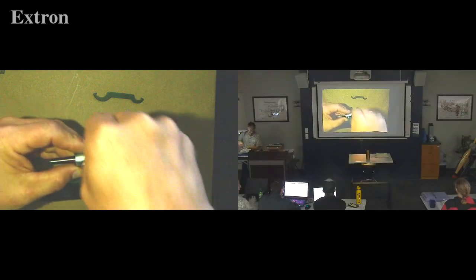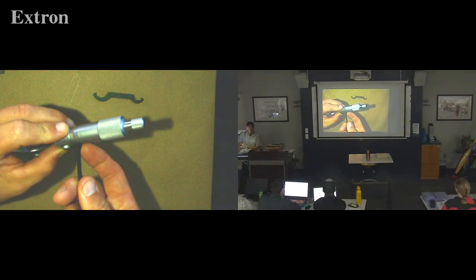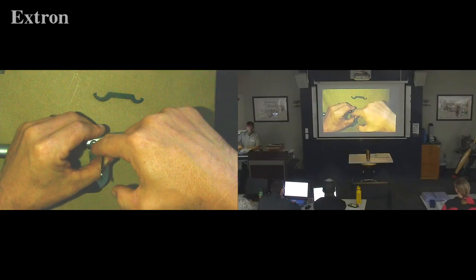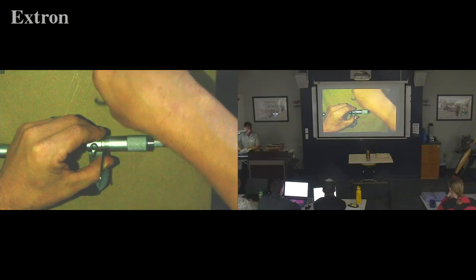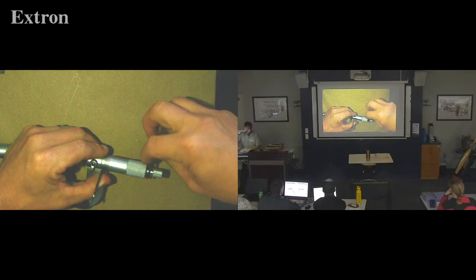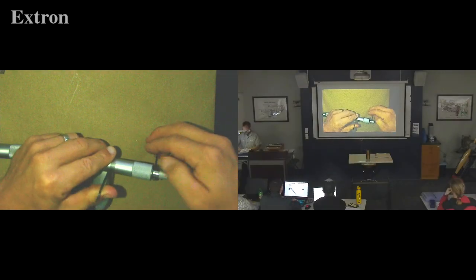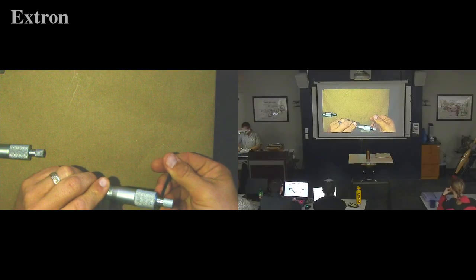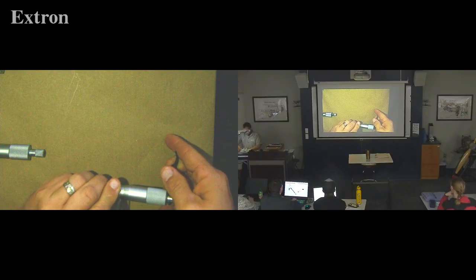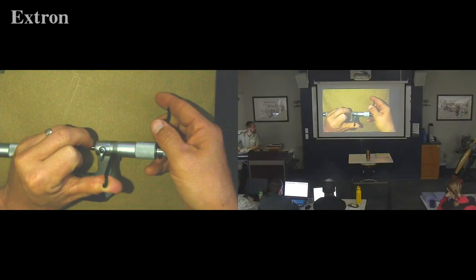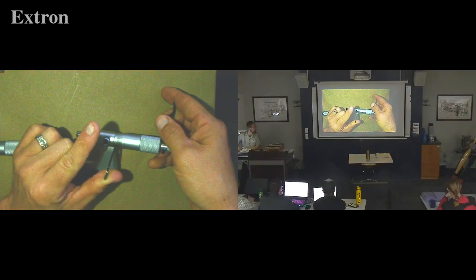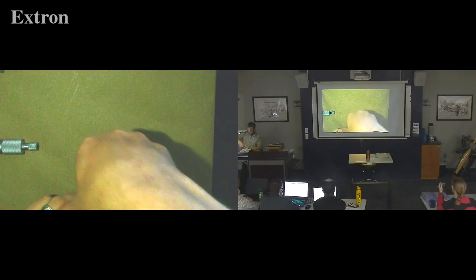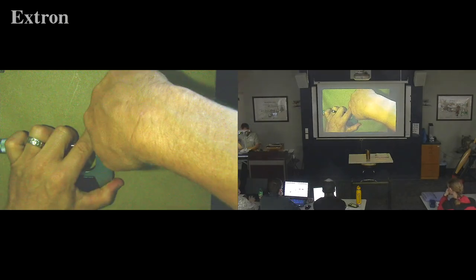Alright, so instead of going this direction, I need to take the hole and go the other direction. So you lock that one in there. The actual micrometer itself is still locked. And then I'm gonna take this guy here. Sorry, I have to think through this too. As I told you, I have a digital one at home. So nice. Okay, so I just barely moved this one here. I moved it towards the zero, just a smidge too much actually. Let's go back. Doesn't take much.